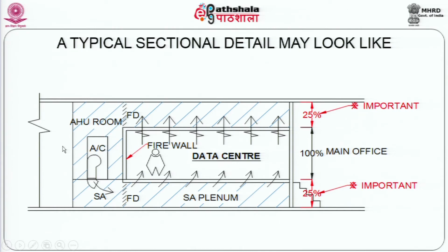Very rarely a small quantity of fresh air is added here, because there is nobody here who needs fresh air. It is enough to say that infiltration exfiltration provides for fresh air, or as a theoretical exercise one may provide for a very small quantity of fresh air to be added into the return air before it goes into the machine and it is recycled this way.